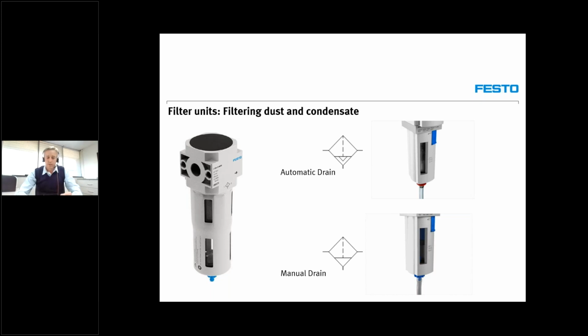Yeah, Russell, I completely agree with you because yes, you do not need daily maintenance for the automatic drain. But as I mentioned, you could fall into the trap of thinking that my automatic drain is draining, and it's left outside of the building, and then you do get a piece of rust that gets stuck in that mechanism.